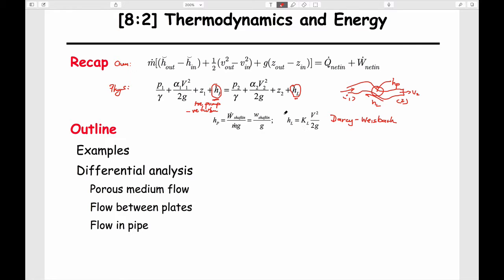But it talks about how much the head loss occurs as a function of a loss coefficient and V squared over 2g, the velocity head. And so we know from this that since V squared over 2g has the units of length, then this has to have no dimensions. Typically, and we'll talk about it in pipe flows, this number is of the order of 0 to 1, but can also be larger than that.